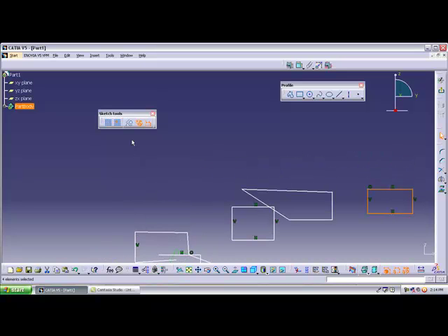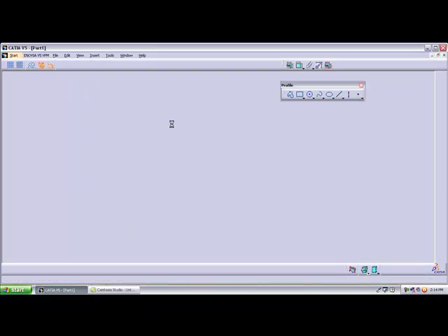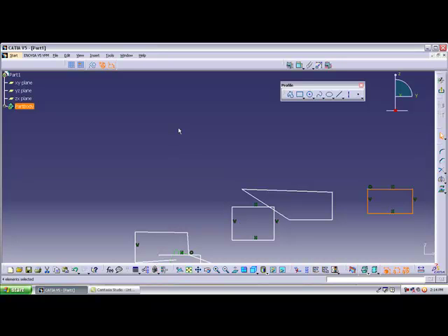So in Sketch Tools, if you turn off these two things, one is the geometrical constraints and the next one is the dimensional constraints, you should compulsorily check them. If dimensional constraints are not working, the icon is turned off. So this is the Sketch Tools, very, very important. Right now, geometrical constraints are about making a relation between one object and another object by geometrical properties.